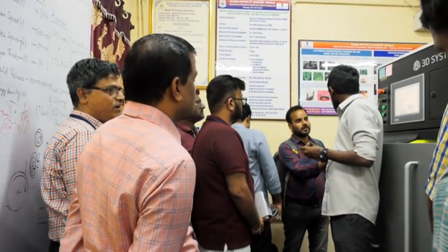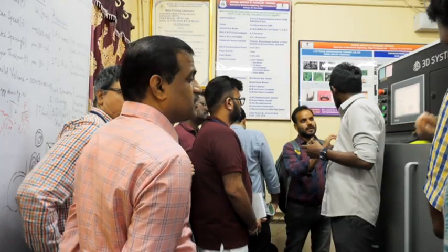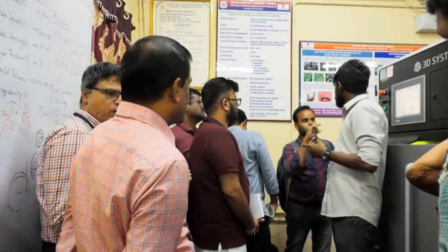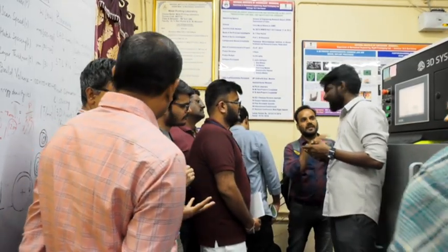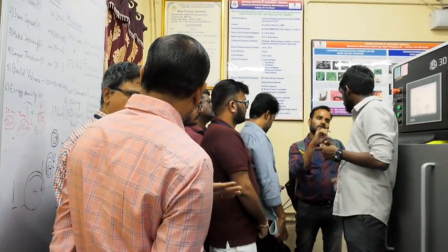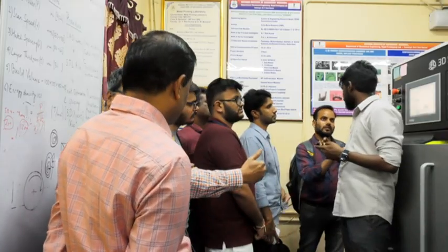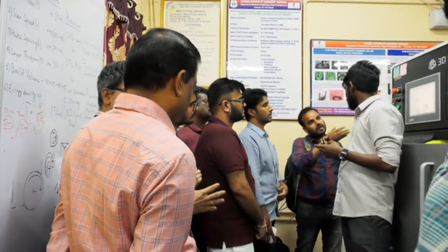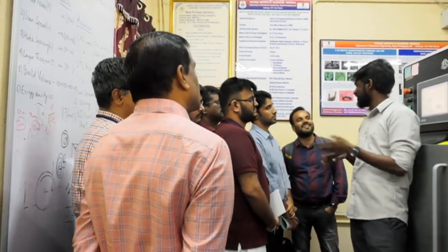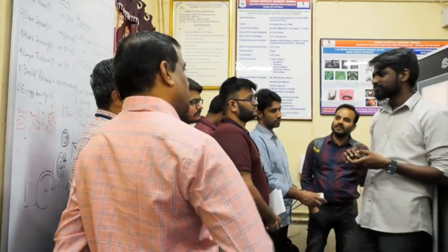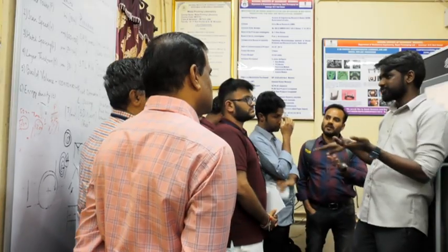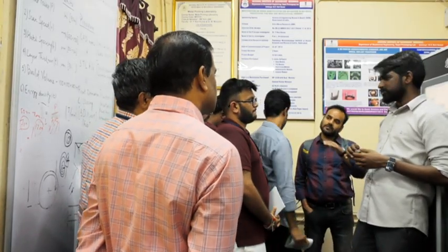You have the dispenser. On that dispenser, do you see any residual powder that won't be able to be used? The dispenser is below that level, so we need to have extra powder in that. Is the dispenser at the same level as the filter? Actually, in this machine there is no extra powder, sir. In this case, the build platform and recoater, the dispenser, are at the same level.